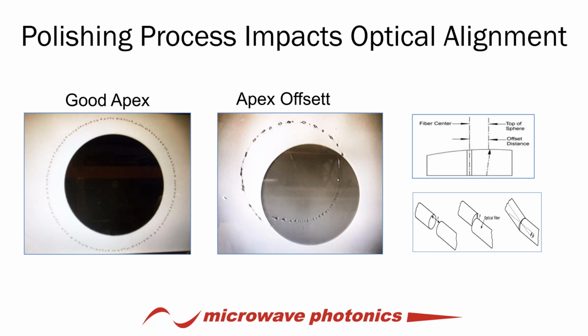And if you refer to some of the earlier slides where I showed the different types of fiber cable, for single mode fiber we're talking about a 9-micron center core of fiber. That's extremely small. So if you get this offset alignment between two mating connectors, that's going to cause a reduction in power. That's going to cause increased back reflection, and that ultimately is going to present itself in a transport solution, consuming loss budget, and in RF it'd be essentially loss and link gain.